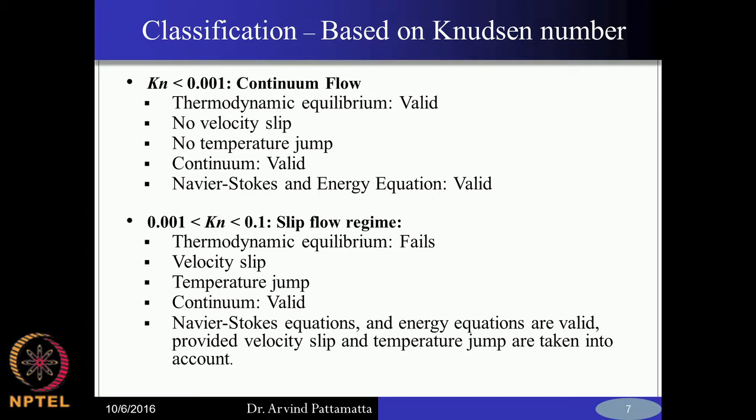Okay. So the slip is only our model. In the real experiment, if you go to the microscopic picture, it is basically a local non-equilibrium, and this local non-equilibrium cannot simply be accounted for in the continuum equations. It is difficult to patch the transition from the local non-equilibrium near the wall to a continuum away from the wall. That is why people resort to these slip boundary condition models, which can account for it in some arbitrary manner, with some empirical constants. You just model this non-equilibrium by another continuum approach, with some empirical constant which might contain some information. But this is not a very rigorous method.